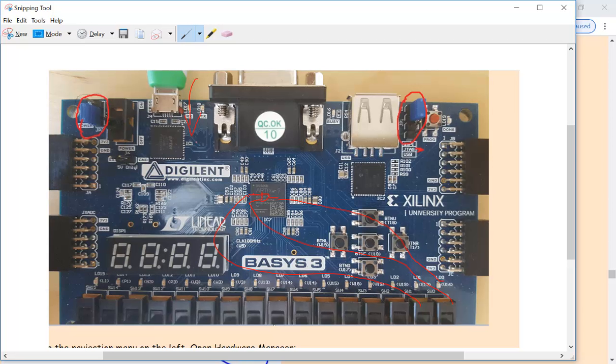So I showed you the example in the lab. The secret is over here. The file name is not a bit file, it's called a bin file, .bin. And the tutorial shows you how to generate that bin file. You have to upload that bin file, just follow the procedure, and it's being uploaded to where? To the bottom of the board. I don't have a bottom view of the board, but at the bottom, there's a memory chip. It's an IC, an integrated circuit chip, and you're able to program that IC chip.